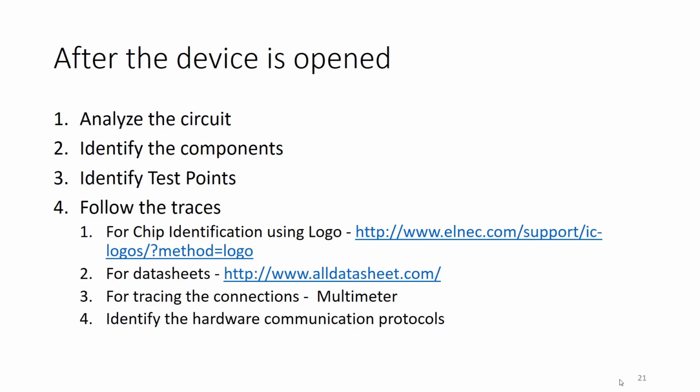We need to analyze the circuit of the board. We need to identify the components available on the board. We need to identify the test points which connect one component to the other components. Then we need to trace this information.